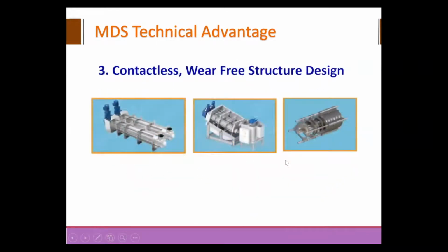Number three, contactless wear-free structure design between the sludge water separation devices and shaft in the dewatering part prolongs the service lifespan of the shaft to over 10 years and rings over 5 years. Due to the longer service lifespan, the downtime is minimal and directly increases the treatment capability and effectiveness.